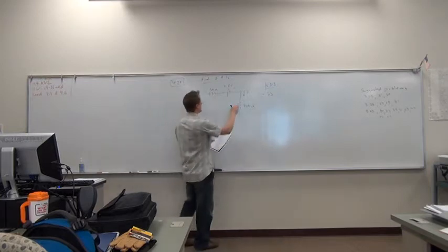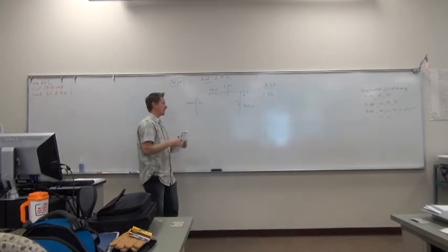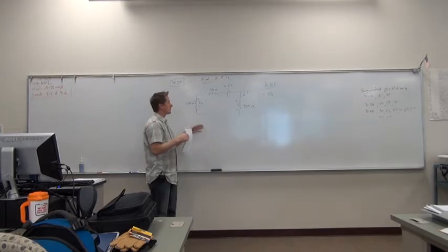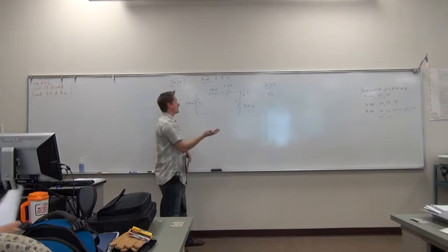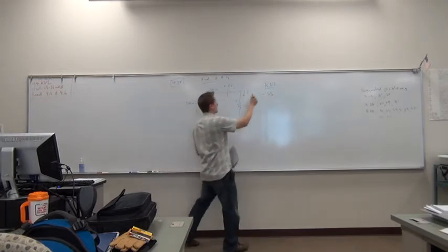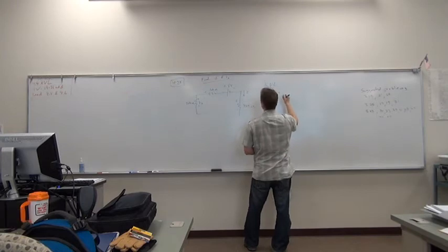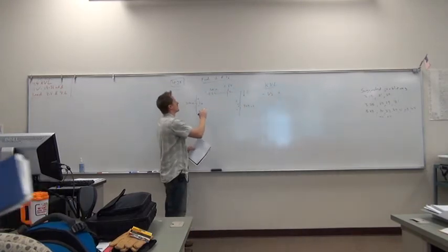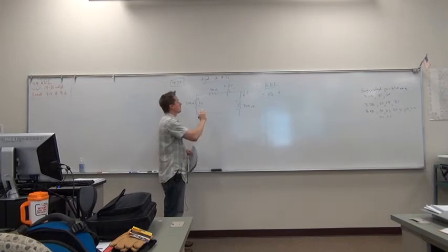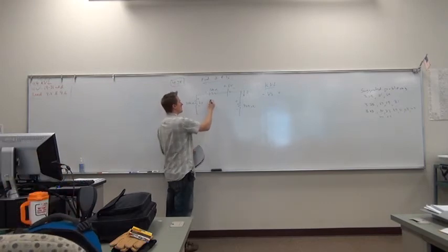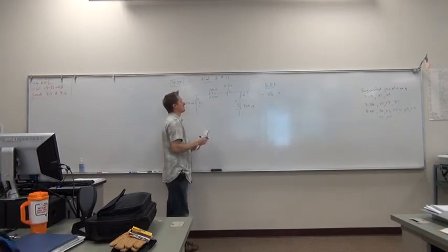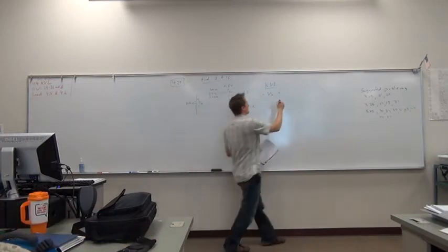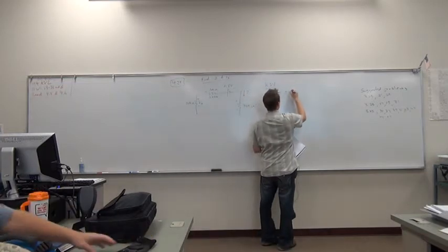Okay. And for this one, if we're assuming I is flowing this way, then the voltage drop across that resistor would be as indicated there on the board. So now that we have a reference voltage, we can complete KVL. We go through this resistor. We get plus what? What's the voltage drop across that resistor? We don't know it, but we can say that it's equal to I times 10K, right? Okay. I times 10K.